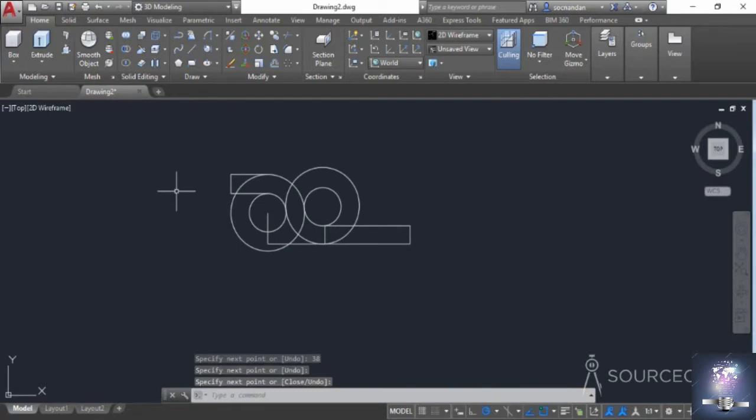Now we'll remove all the unnecessary parts from this drawing, and for that I'll select the trim tool. So select the trim command, press enter, and now start with this part of the drawing which is not required, and also click on this part. We are not able to trim this part, we'll take care of this later on, but before that I'll click on this part and also click on this part. Remove this portion and remove this portion. Now remove this one,